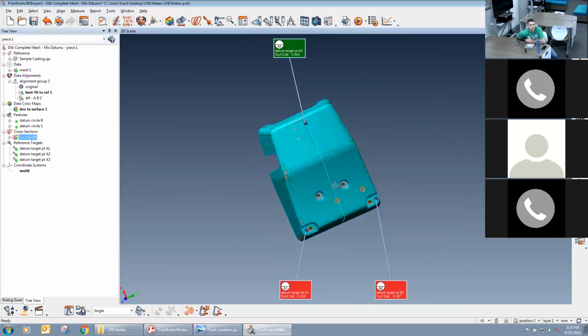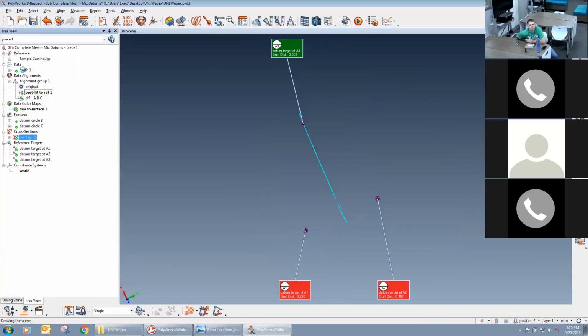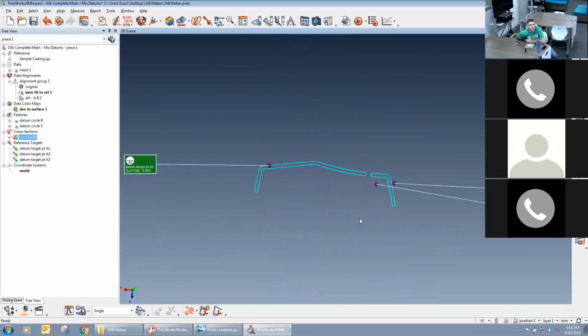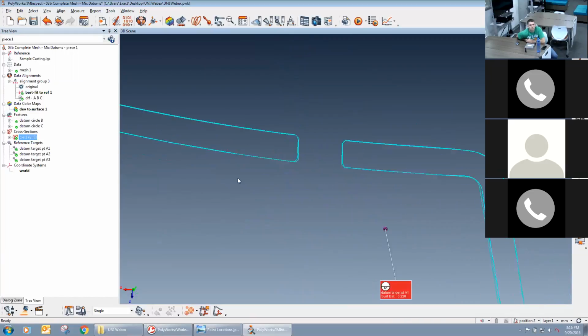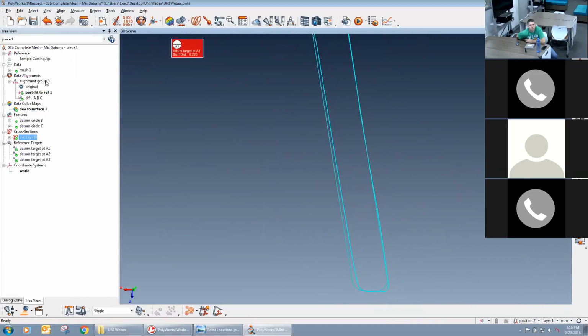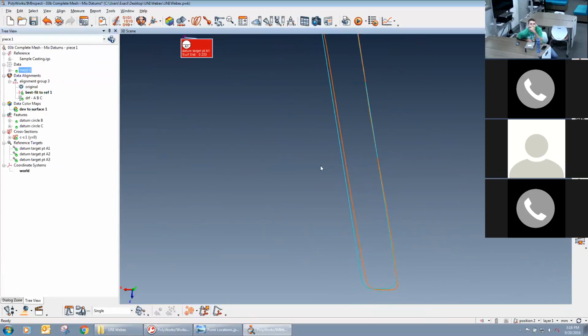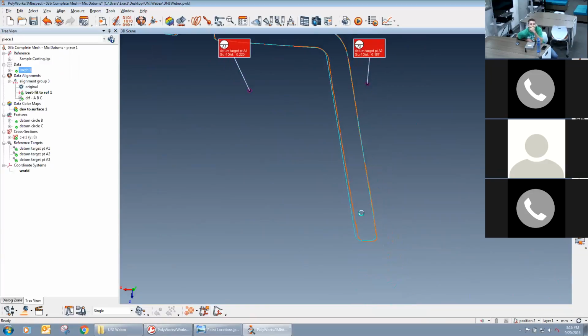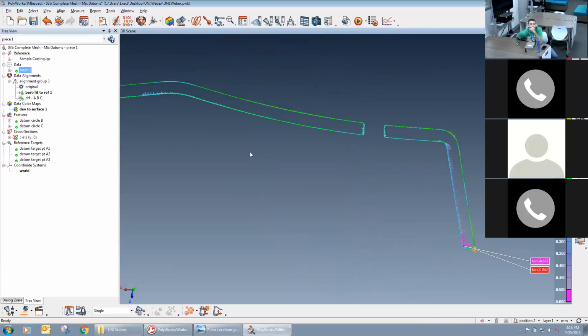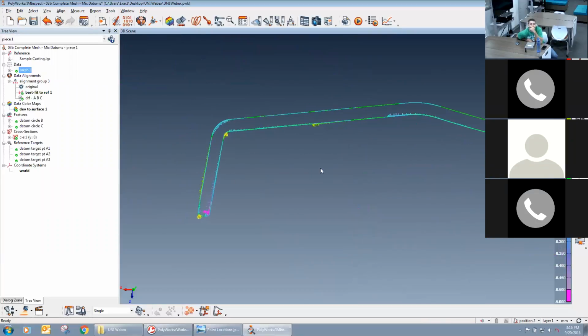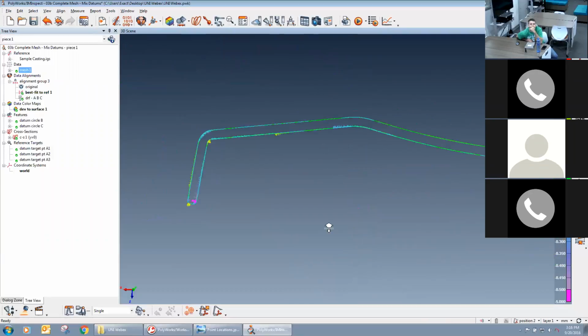And it's made here. So if I hide the mesh, and hide the data and hide the CAD, there's my cross section. You got to zoom pretty far in here. Oh, here we go. Let me change the color of the mesh real quick. It doesn't look very, there we go. Orange is the scan and blue is the CAD. So we can look at that same deviation. If I turn back on the color map, here with the icon to the right, I get a whisker plot of that deviation that matches up with the color from the scan.